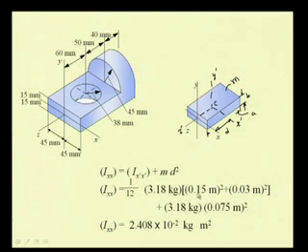We have the dimensions A and B, and the thickness is nothing but 15 plus 15, that is 30. So, in terms of meters it is 0.03 meters. So, this quantity is the second moment of the mass of this element with respect to its centroidal axis plus mass times the distance d, that is 0.075 meters.